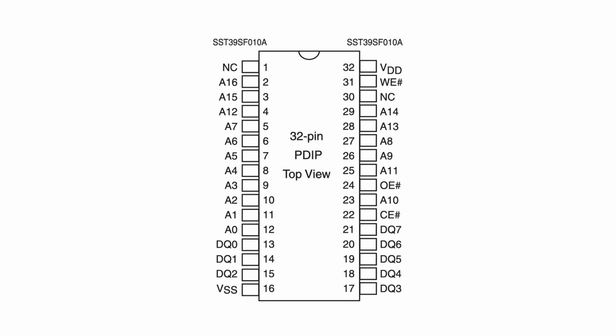So that will work to generate our read and write strobes, but I want to think a little bit more about the flash ROM, specifically the write enable signal. I want to be able to reprogram the flash ROM in system, but I don't think I want to be able to reprogram it accidentally. I kind of want to have an explicit write enable for the flash ROM, which is something that I should be able to control with a register that will be used to bank the ROM.